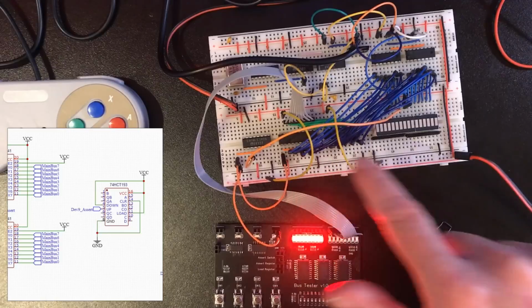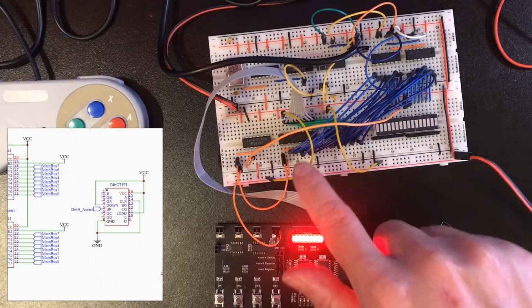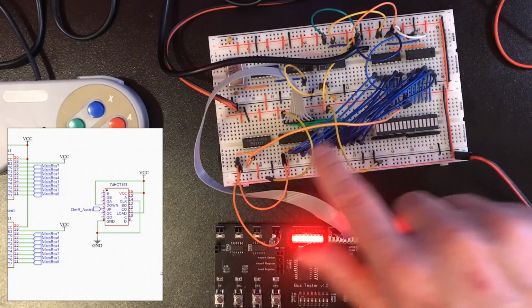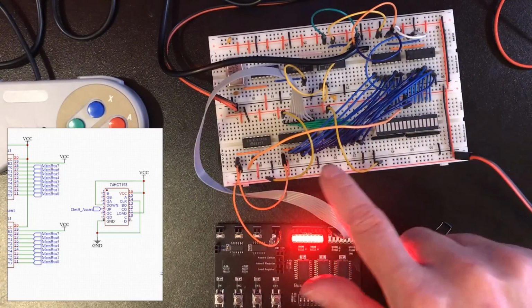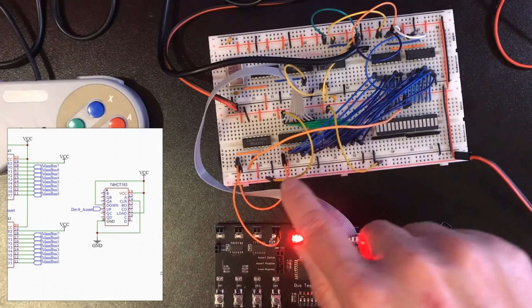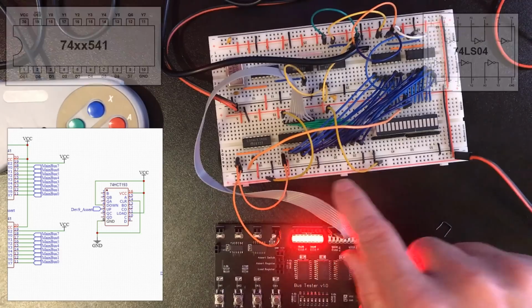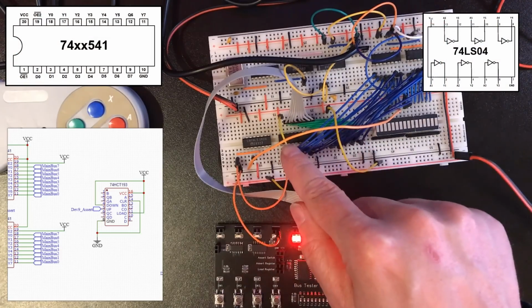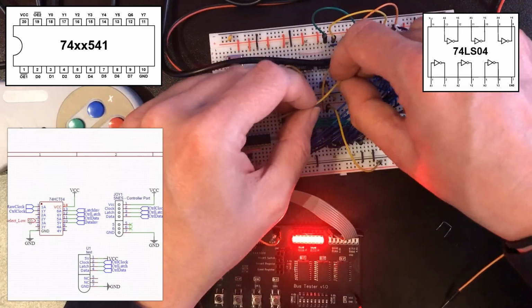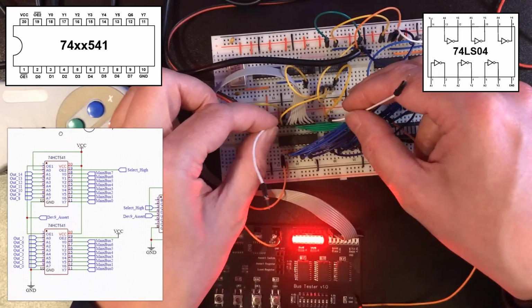Now, using this to enable the active low enable lines on the chips, you've probably seen me build the circuit before with a 138 demultiplexer. And that would give me the option to both do the selection and enable the outputs singularly with the active low load line. But the line drivers we're using here have the 2 separate enable lines, so we can avoid that. We just need this enable line to be the inverse of this one. So we'll take the output to one of our spare inverters, use the output of that. Let's temporarily visualize those.